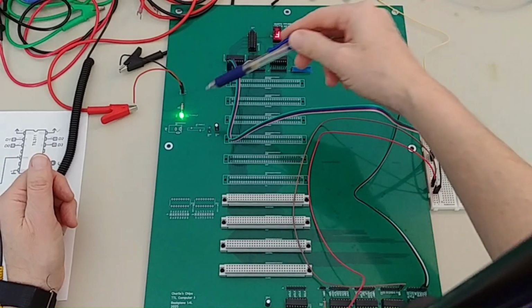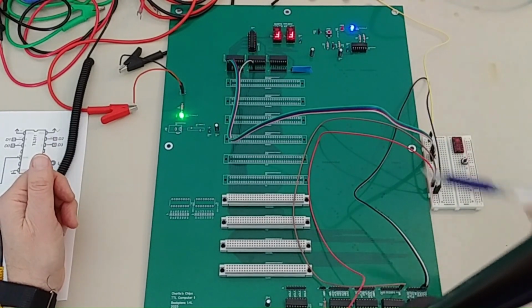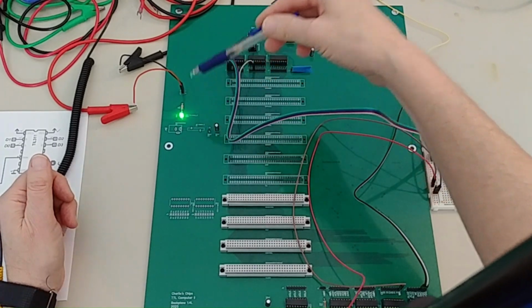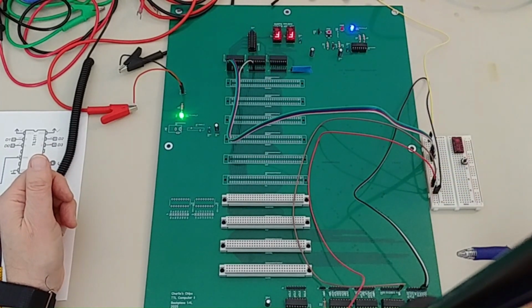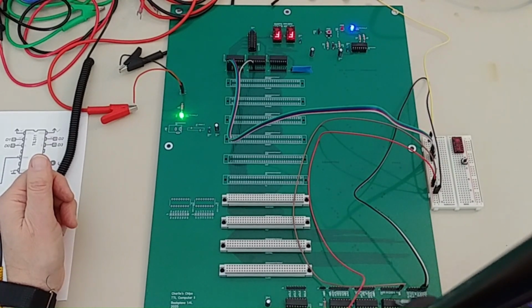So the main issue is going to be the thermistor here, the inrush versus the resettable fuse. And again, I have concerns now about these pull downs needing to be 1Ks, but we hopefully will be okay. So that's it for today.